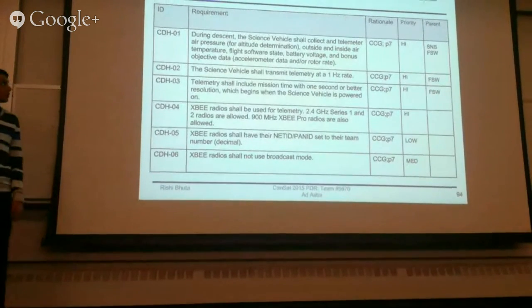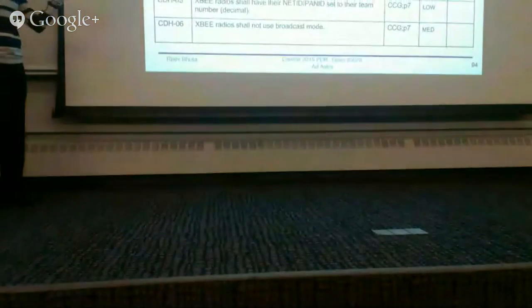So the overview requirements of this group. Here's the trade study we did for the microcontroller. We chose this one because it fits all the requirements of the mechanical process. It has 14 different pins that operate at 5 volts, and it can provide 40 milliamps. It has 2 serial input outputs to receive and transmit TTL serial. And it takes 6 to 20 volts unregulated or 5 volts regulated.